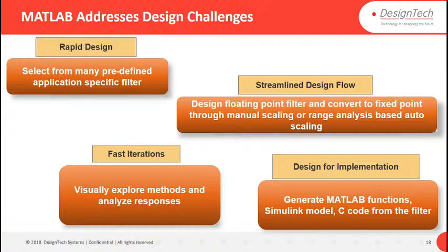About design for implementation: we have MATLAB Coder to generate C++ code, and Simulink Coder to generate C++ code from Simulink. If you want to deploy on embedded hardware, in MATLAB you have Embedded Coder also. And if you are working on FPGA boards and want to deploy your filter on them, there is HDL Coder and HDL Verifier also. So it depends on what kind of hardware you have.